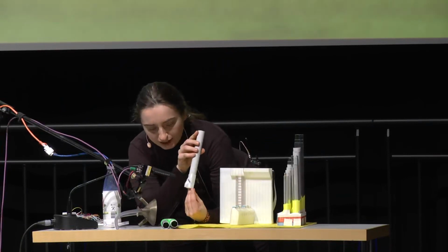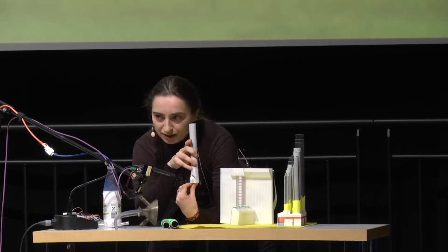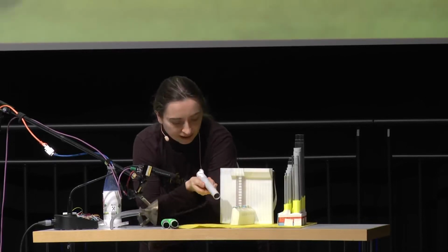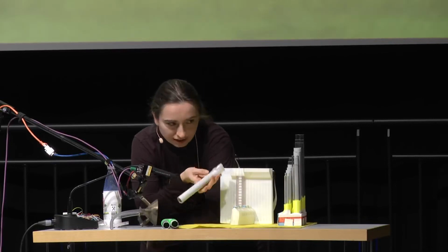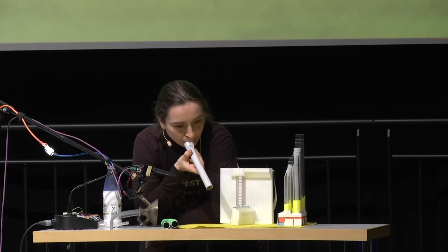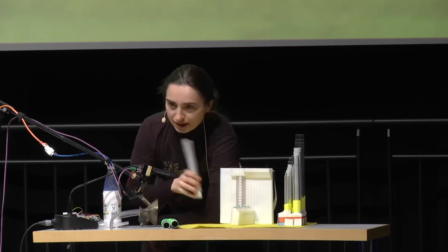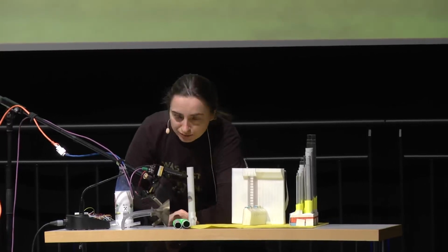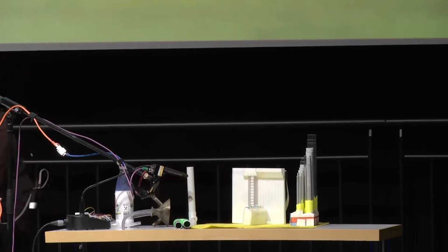I did that because I always printed them at a 45-degree angle, and all the flue pipes had problems with the support materials. And if I make the labium at 45 degrees, then I can print them upright, and it'll stick to the building plate, and there are really no problems with that. It makes sounds just like other flue pipes, and that's all fine there. I couldn't find any difference really if you build it at 45 degrees or straight up.